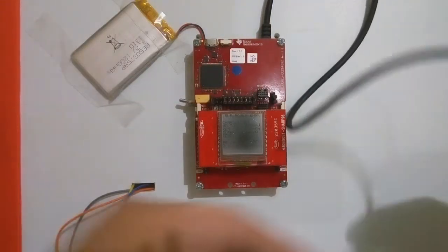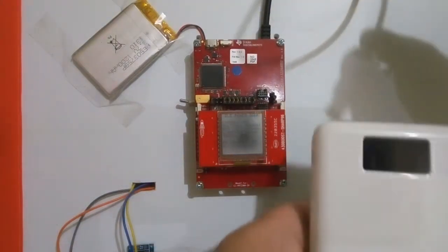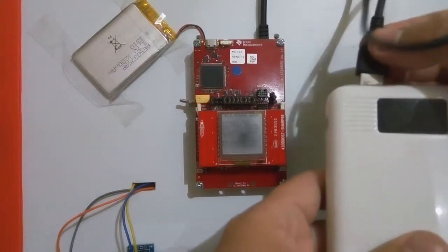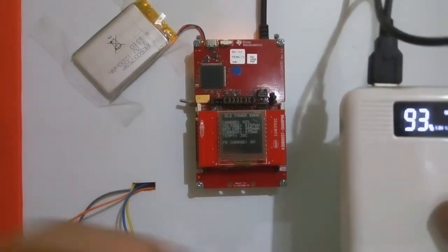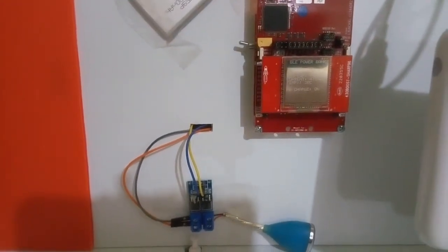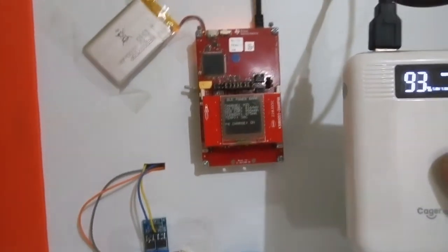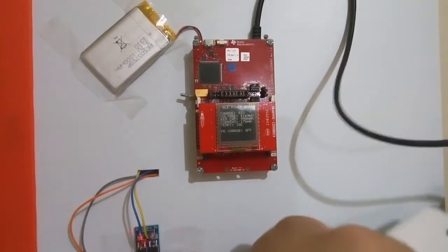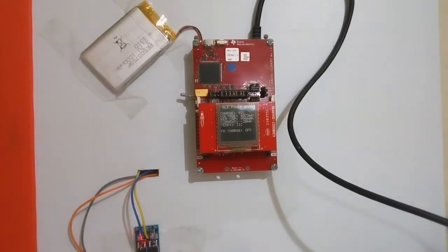So to charge it up, I will connect it to a real power bank. Okay. Connect it. And it wakes up from shutdown mode. Okay. So when it's charging, the MOSFET board is off and will not allow 5 volts to pass through the USB port. Okay. So you can see the PB charge off status change from on to off.